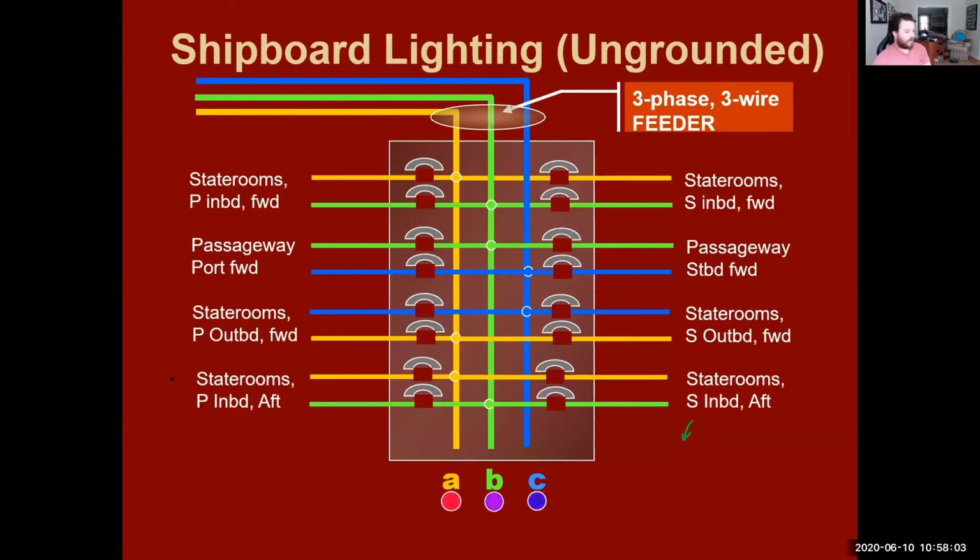So the way we would locate it is, we know A is the problem. Green is B, blue is C. Now as we go through, we're going to slowly flip this switch first. Did the light go off?